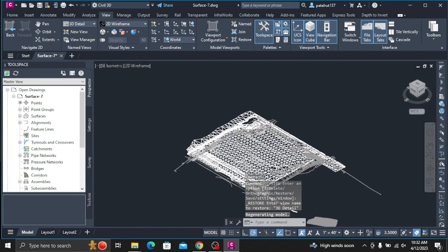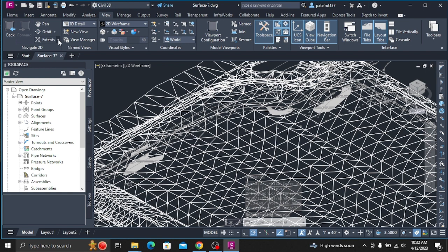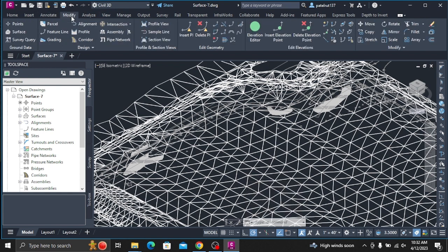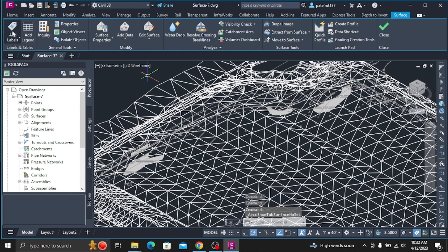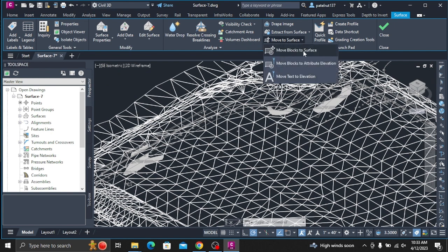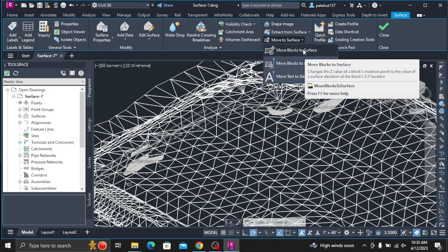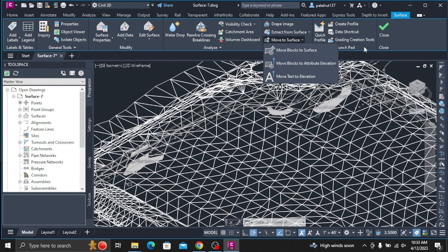This exercise uses Surface 7.dwg with the modifications you made in the previous exercise. In Tool Space, on the Prospector tab, expand the Surfaces collection. Right-click the XGND surface. Click Surface Properties. In the Surface Properties dialog box, on the Information tab, specify the following parameters. Render material, site work, planting, sand. This render material displays contrast in the surface elevations. Surface style, standard. Click OK.